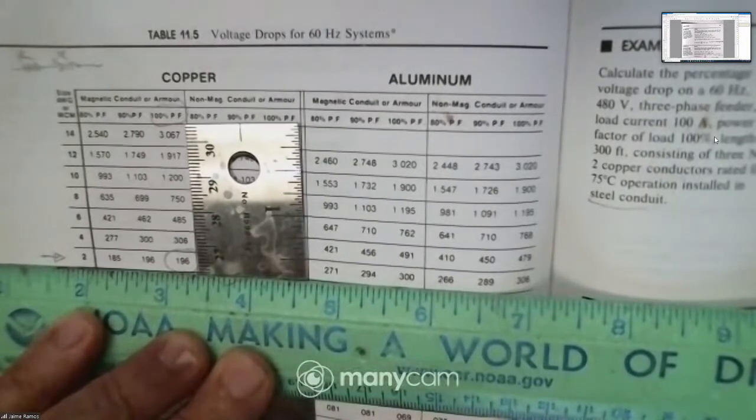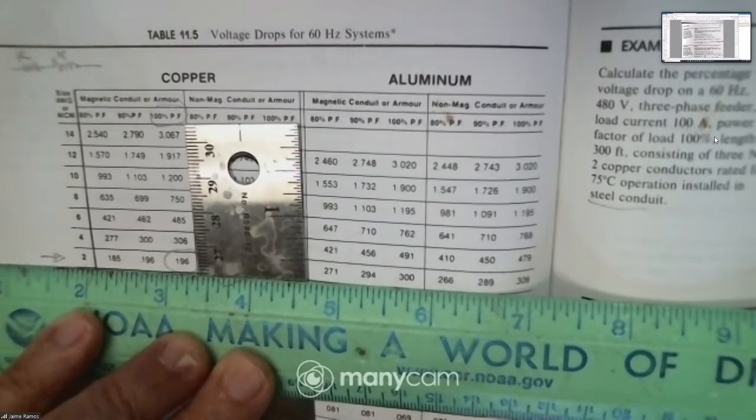Now, for this case, the length multiplied by current is 30,000 ampere-feet. So that's why in the second row of calculation you can see 0.196 times 30. Therefore, the voltage drop is 5.88 volts. This voltage is line to neutral. Line to line is 10.2 volts.